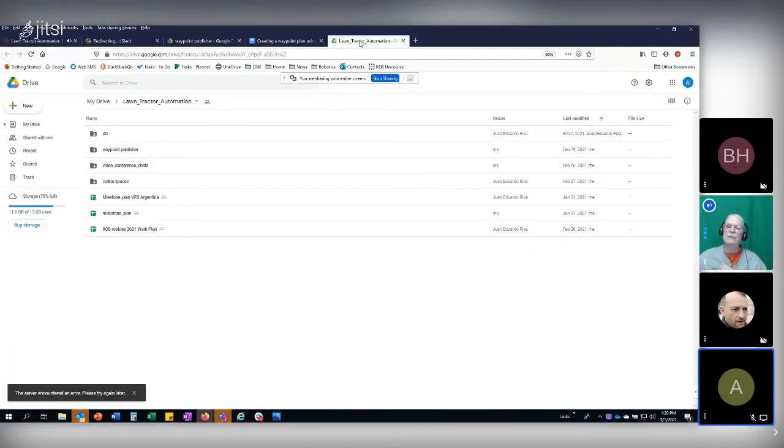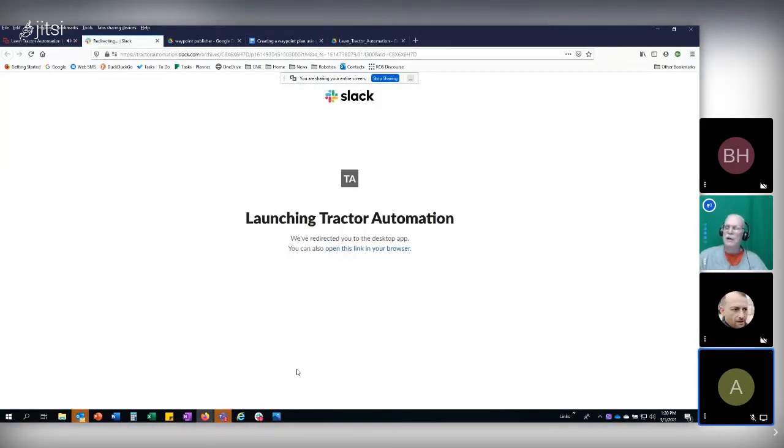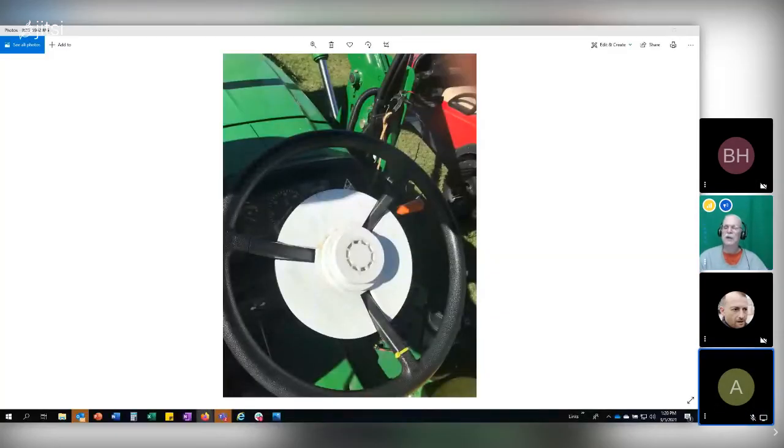Anyway, I've got that sensor. It's a Hall effect sensor. It's got an arm sticking out, so I can connect the arm of that to that one arm that moves back and forth that I was just talking about. I might do both, and that way, back to my concept, I like to put on two or three things and then select which one works the best. So I can put that on underneath to read the angle, and then I can put a potentiometer on the motor to read that angle. And there may be some other things I might want to dig into also.